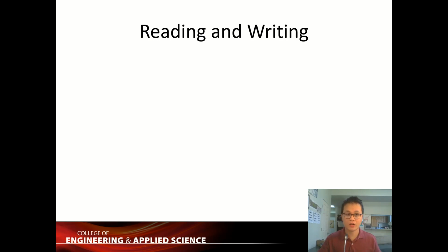Okay, so now we are going to talk about reading and writing. There are some procedures or steps that you need to perform in order to read or write into your memory. For the purpose of transferring a new word to be stored into your memory, there are these steps to be followed. First, you have to apply the binary address of the desired word into the address line.